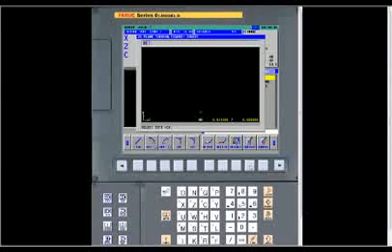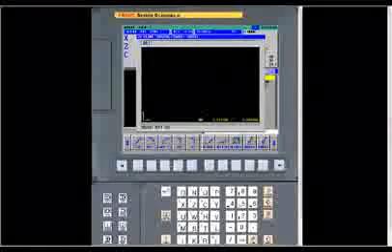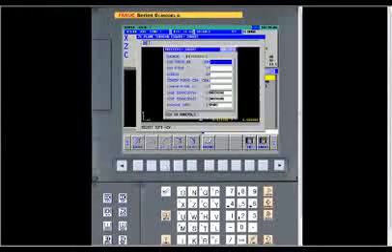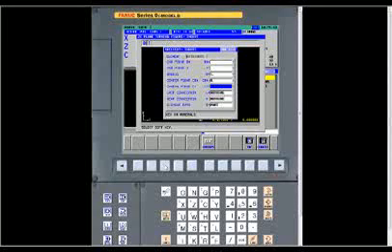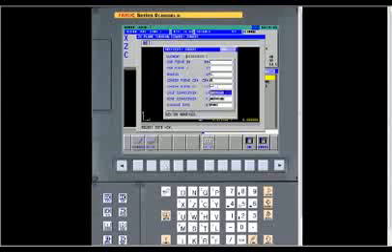And at this point, it doesn't really have any scaling because it's the only part of the geometry we've described. So now the next thing we want to do, we have to describe the arc. And it's a counterclockwise arc. So we press that. And within this, you see how all the first 5 fields all have asterisks. Because depending on your print, you can have a variety of different information here. So what we want here, we're going to tell it, we know the radius is 1 inch. Enter that. We know the center point is X0. And we know the center point in Z, if you draw a complete 1 inch radius, is minus 1 inch.